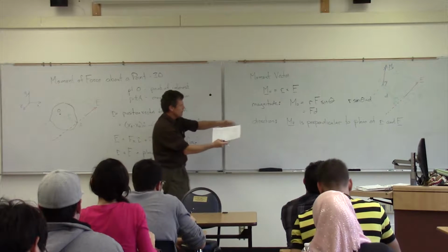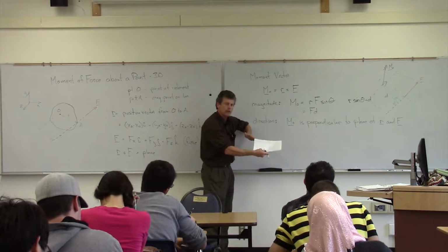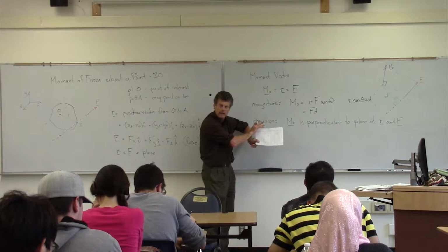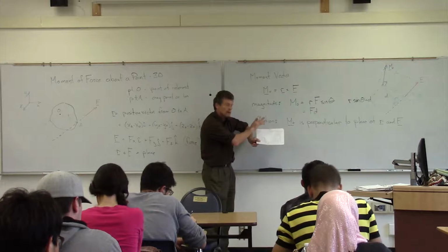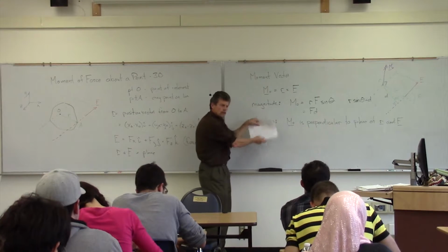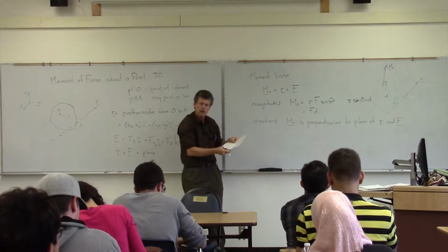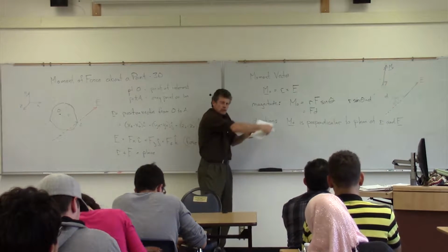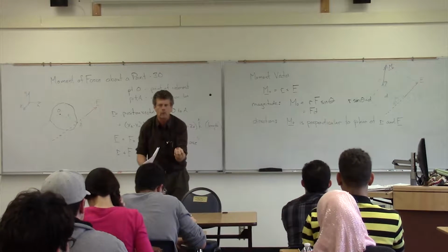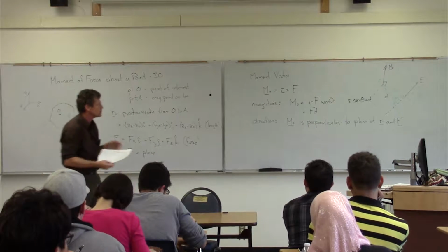So if I have a position vector and a force out here creating a plane like so, then my moment vector direction is going to be perpendicular to that plane. And again, think about it. When we were thinking about it in 2 dimensions, we're going to rotate this way. It's again that axis of rotation. So even in 3-dimensional space there's going to be an axis of rotation created by a single force and that single position vector to that point of interest.